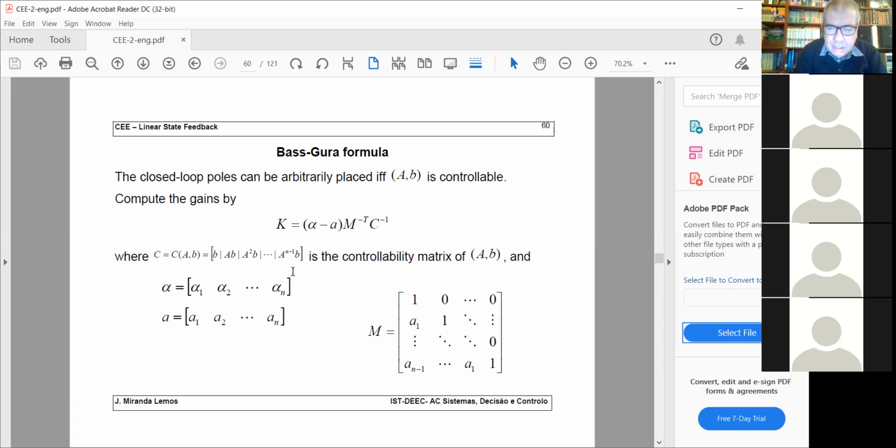So I use the inverse of the table, the static gain. So I have a system with a static gain of 5. So I use a controller, which is just a gain of 0.2. So I apply my reference through this gain, and in the end, in steady state, I have my output following the reference. Does this always work?